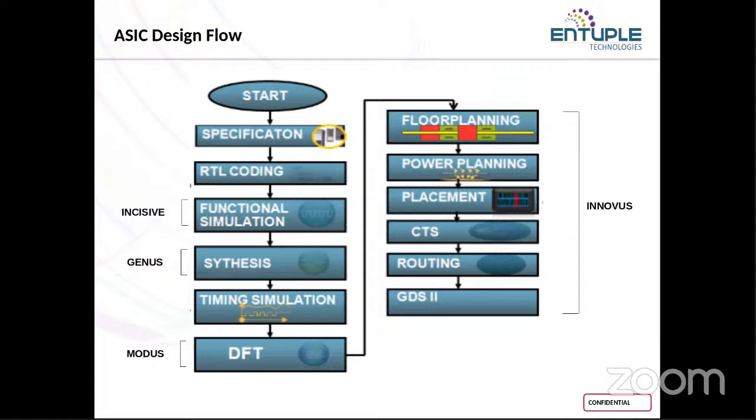Synthesis is always a three-step process. The first one is your translation, or generic process. At this translation stage, whatever basic RTL logic you have taken will be converted into basic logic gates.